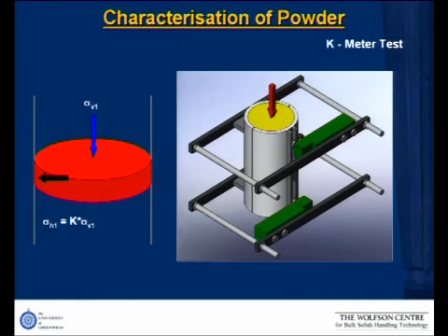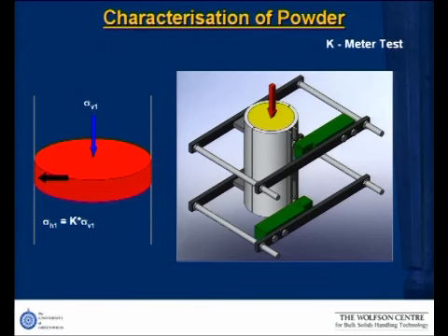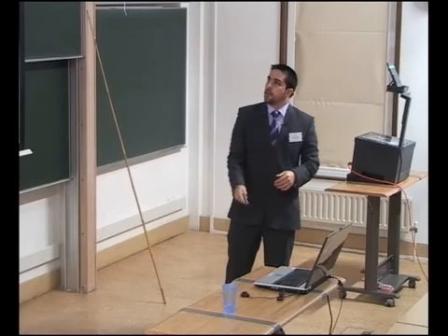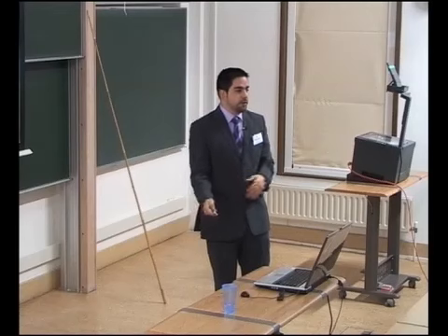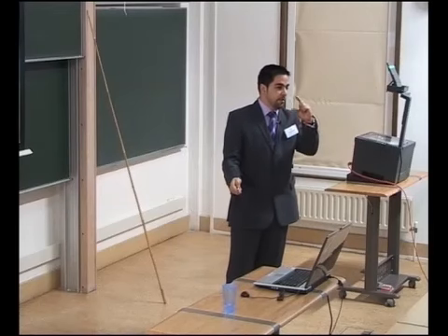So we have a cylindrical ring, you can call it like that, and then you cut it in half, as you see here and here, and then you have two load cells here, and we apply a vertical force here and sense the horizontal stresses in this direction with the load cells. Why two? Just for the stability of the system, and to get better results.